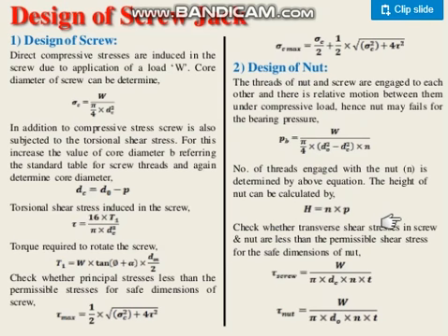Yes, here. Okay, now this will be pi dc, and this is the thickness of the thread, and how many are there, N. So pi dc into t into n. Okay, this will be the area. Okay, from this you can find out the shear stress.